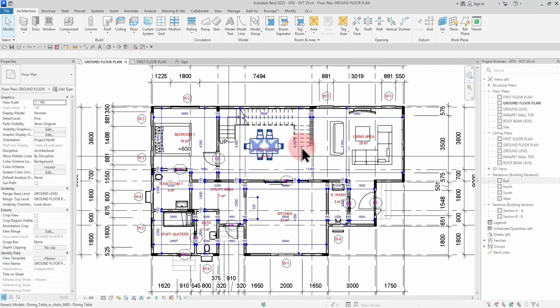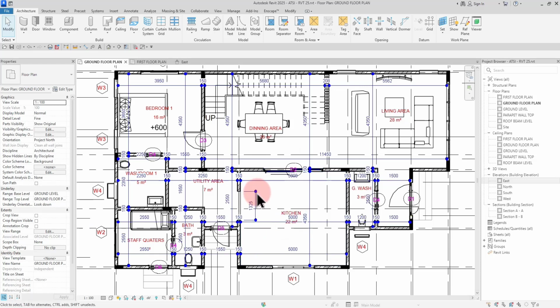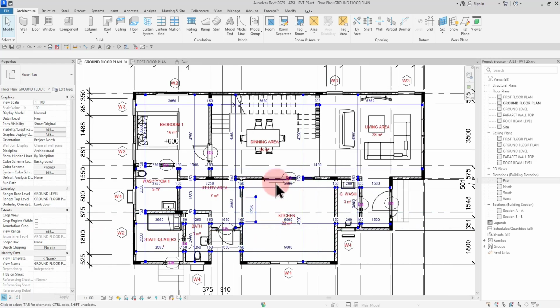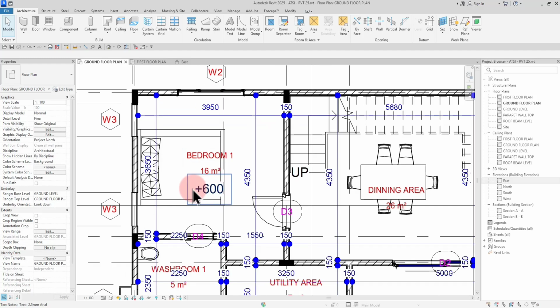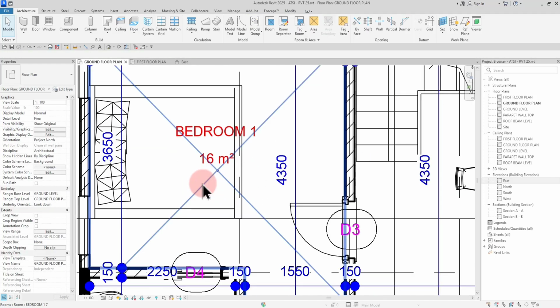But you will notice I have some different spot heights. You will notice that I stepped some floor slabs down to actually preserve in case that area should flood or have some water pouring in, it doesn't automatically walk into the space and get into the living area. So I stepped those floor slabs down about 150. So let me delete this out of the way.